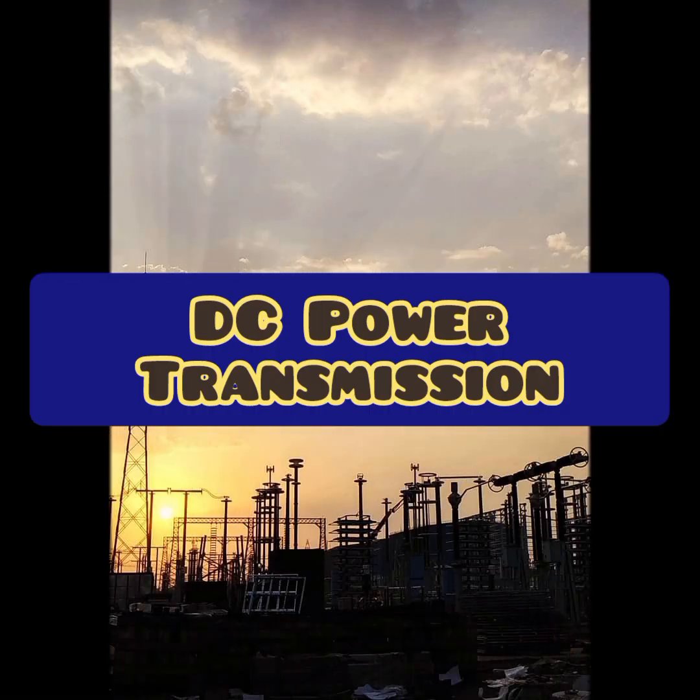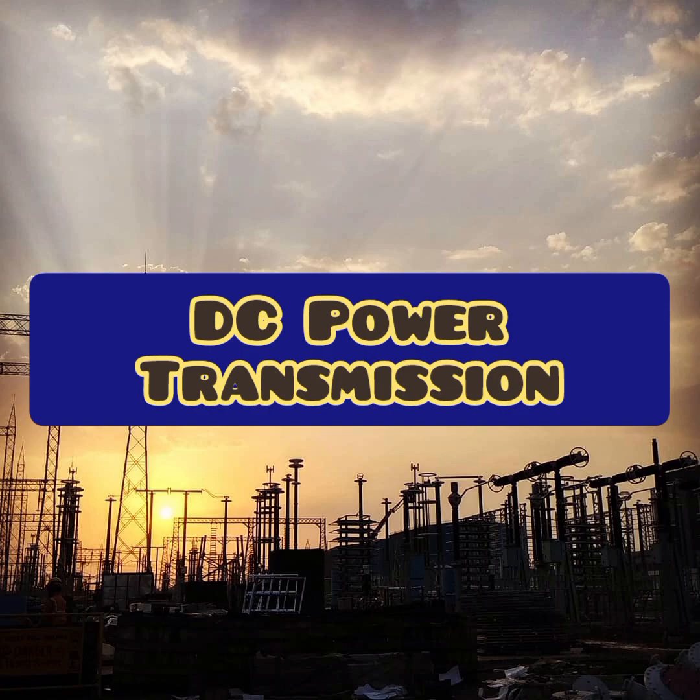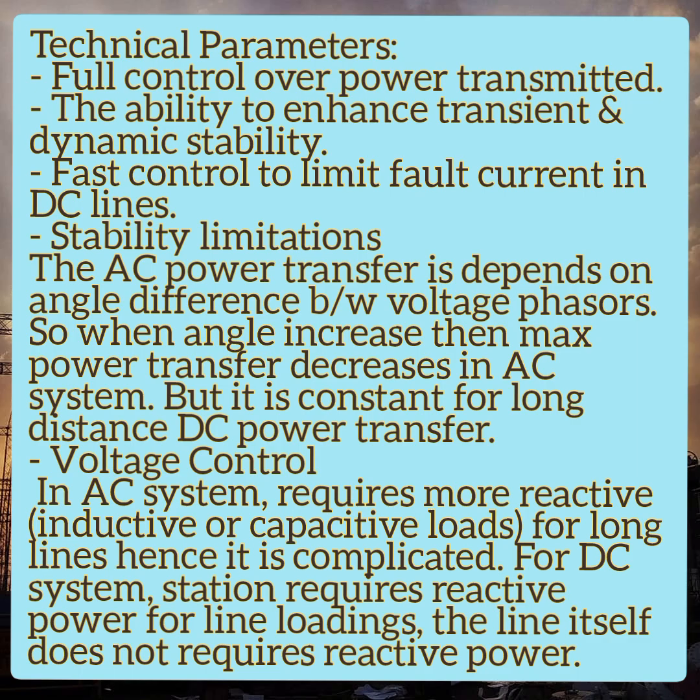Hi, hello everyone. In this video, we are going to see about the DC power transmission in an HVDC system. In an HVDC system, full control over the power transmitted can be achieved. The ability to enhance the transient and dynamic stabilities is also there. Then there is fast control to limit a fault current in DC lines, like by using HSS, high speed switches, breakers.